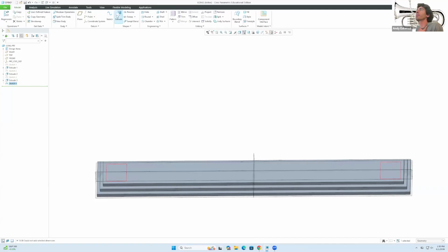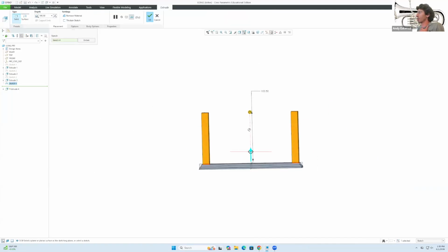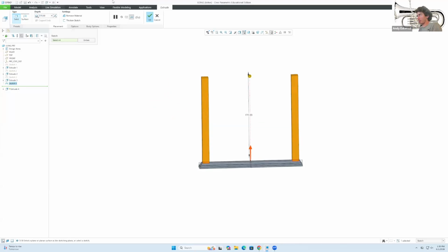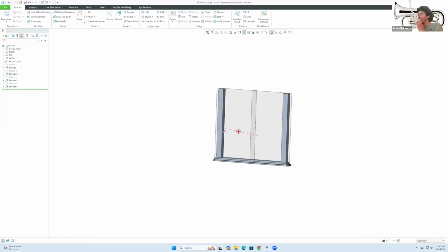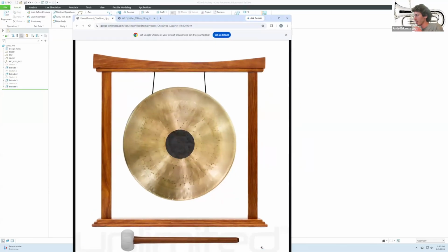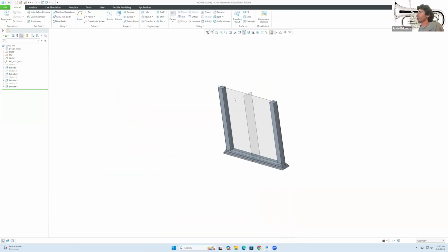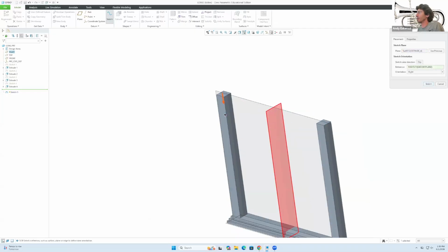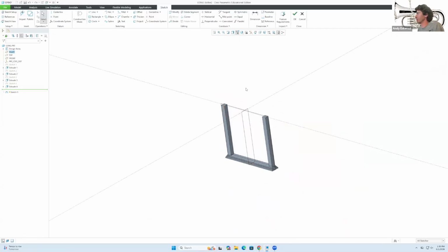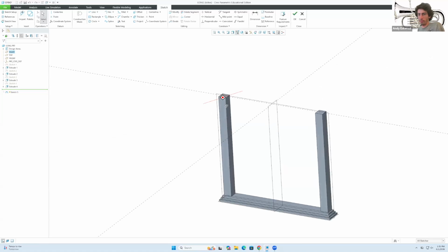We will go here to okay, extrusion, and we're going to make this sufficiently tall. So maybe we'll give it just 150, maybe 170. And say okay. So we have a little gate that we're building in here. So we'll add one more base. One thing that we could do is I'll go here to sketch. I go to this face in here. I go to sketch, and now we are on that top face.